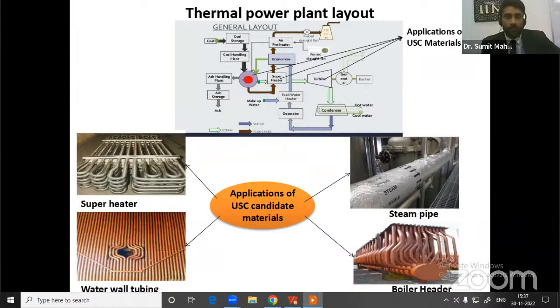So if we are talking about welding, what is welding? We'll discuss how these components have to be joined. Welding is basically a fusion of materials. When there is one material, two materials, with the help of heat, we melt those materials and let them solidify at room temperature. Those two materials will solidify and make a joint, which is called a welding joint. A welding joint is a permanent joint, and we require it to join different components of the power plants. So here is some introduction to the different components and why welding is important.